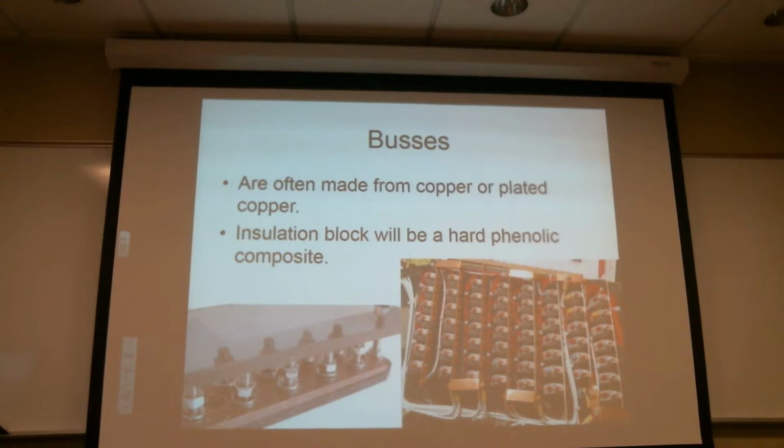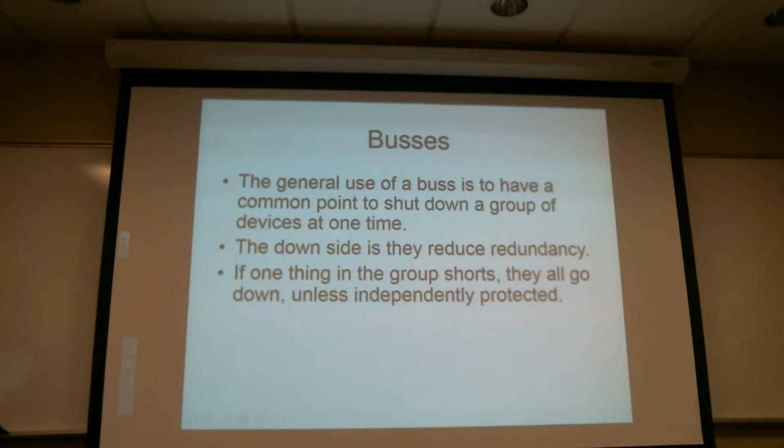Now, one of the things we don't know is what's the voltage drop for that copper strapping. As long as its cross-sectional area is bigger than the total cross-sectional area of the wires going to it, for that short distance, you probably don't have much voltage drop.